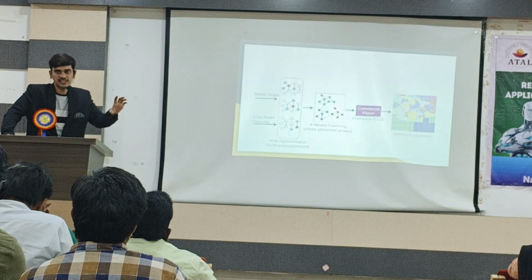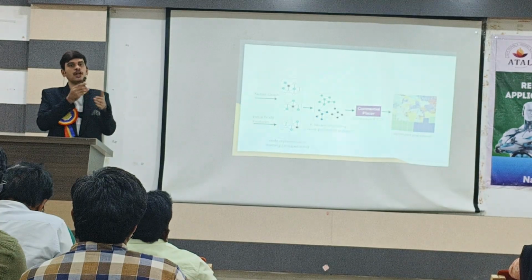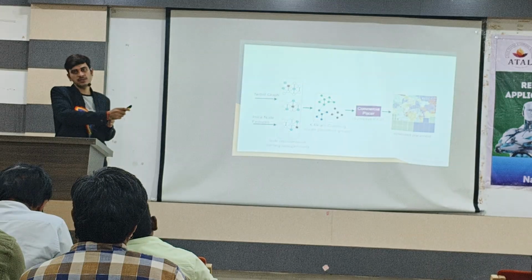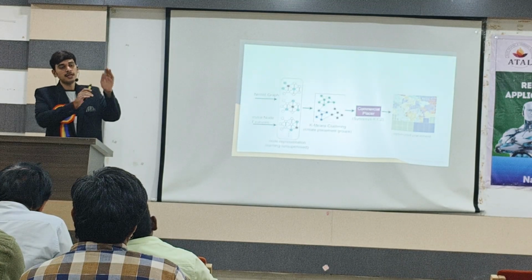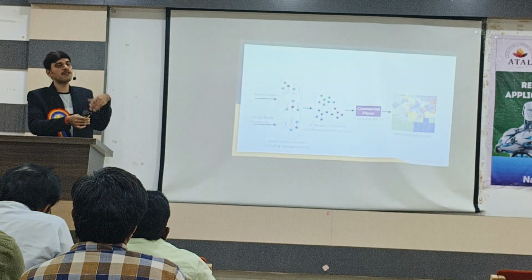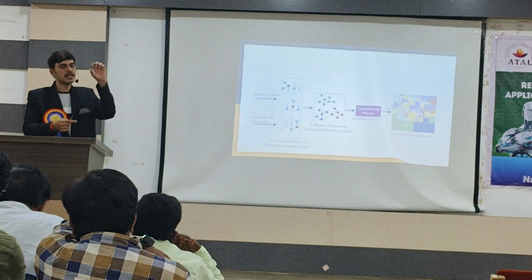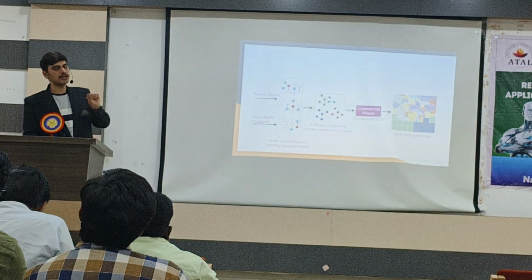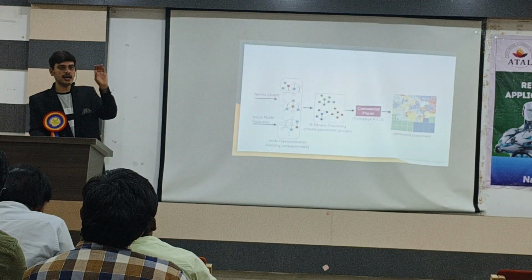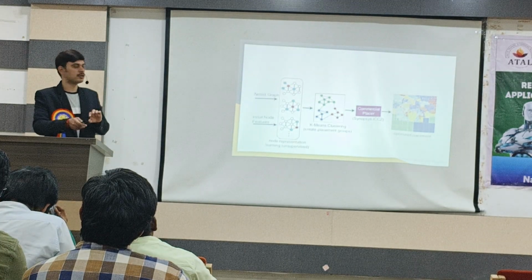Both synthesis and PNR are done in the same group, so that the correlation will be very good. Once the floor plan is done, that floor plan is taken as an input to the synthesis, and based on that, the synthesis tool will synthesize the cells, like whether it is a 4 input NAND gate or a 2 input NAND gate, based on power, performance, timing, everything. It will take all these parameters into consideration, choose the best cell, and use that as the output.